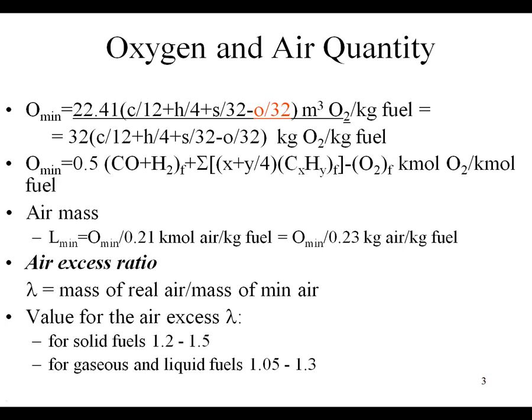If the molecule of nitrogen from the air has no oxygen, because the carbon is stealing the oxygen, this is very good for the combustion, because the combustion is perfect in terms of carbon. You use all the energy of the fuel, but you don't produce NO. You understood? So in special cases, this air excess ratio, for avoiding the formation of NO or NO2, named globally NOx, can be under 1.